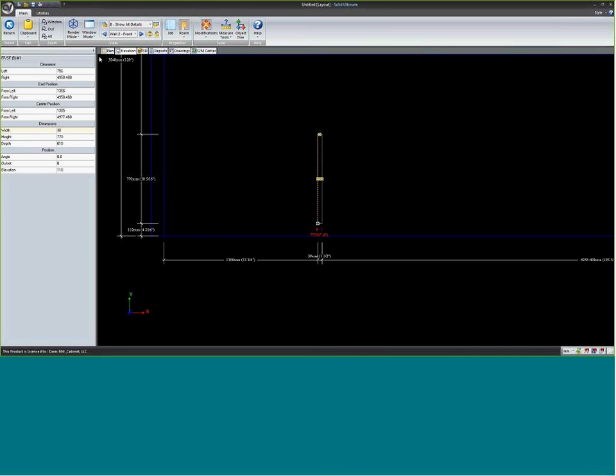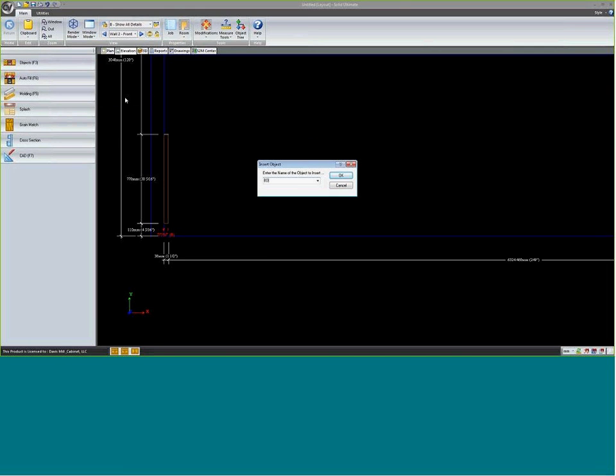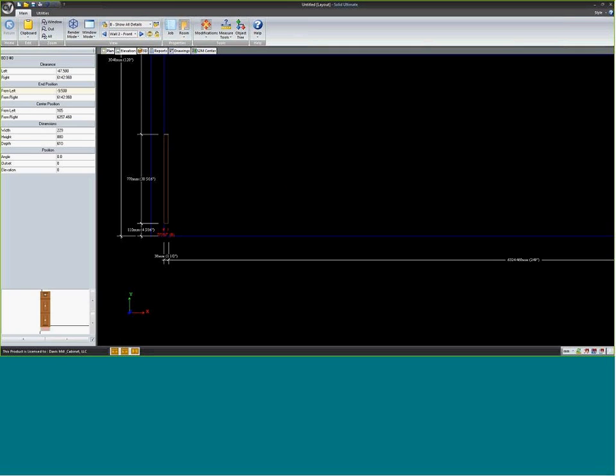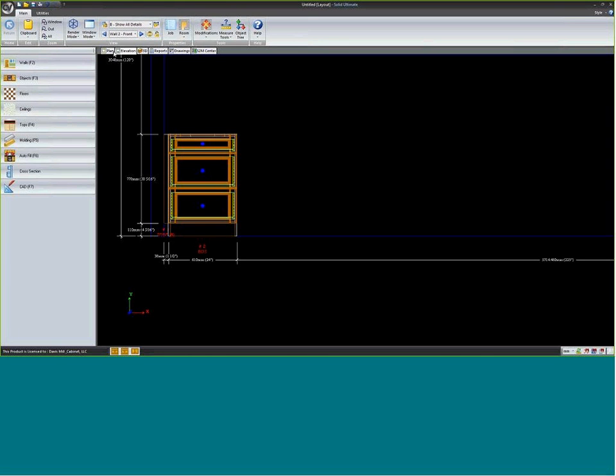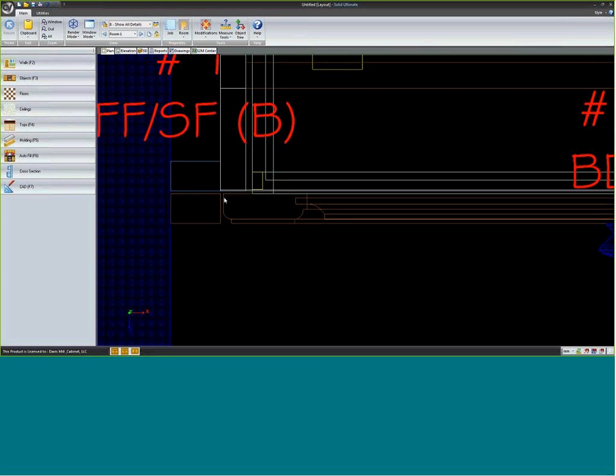Let me show how those are typically used. I'm going to take this and butt it into the sidewall, and then I'm going to insert a BDT cabinet next to it. Just give that cabinet some width. So now if I look at this in plan view, you'll notice the flat filler is back on the case depth. The styled filler is out on the door depth. The idea is to make this look like an overlay filler, a door that dives into the wall that then gives your installer some scribe room.